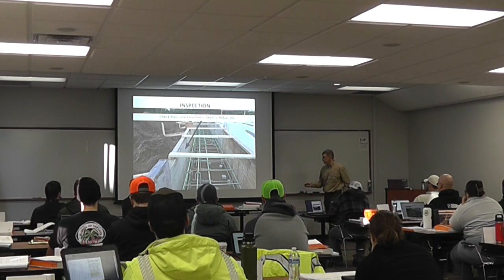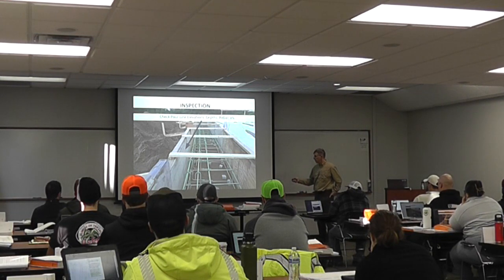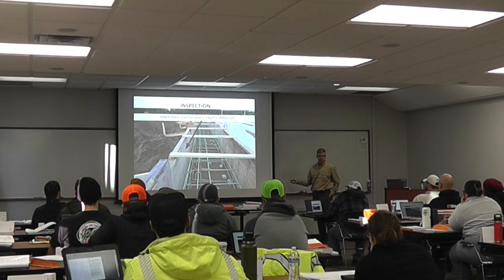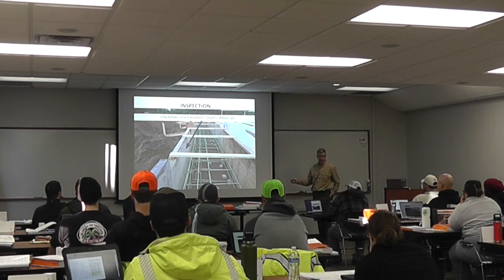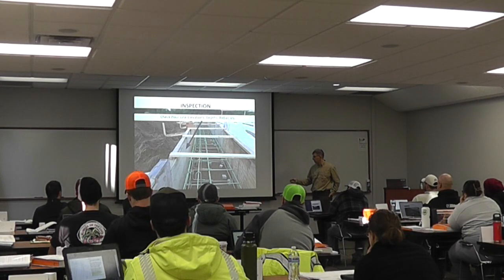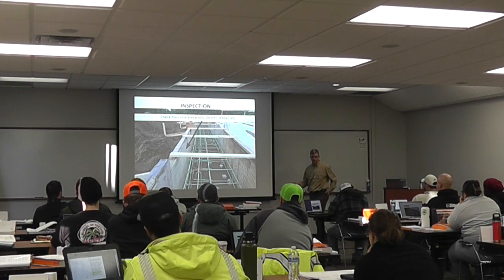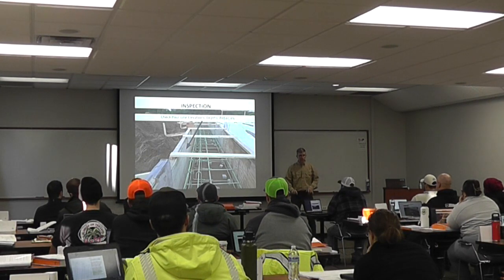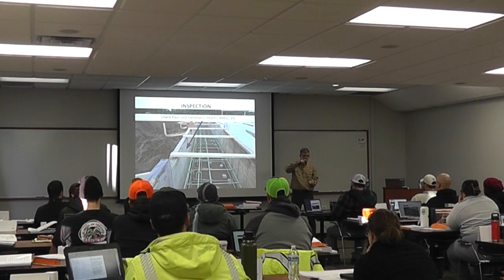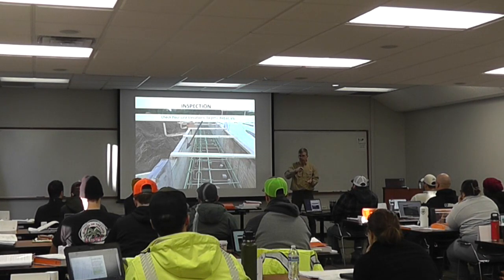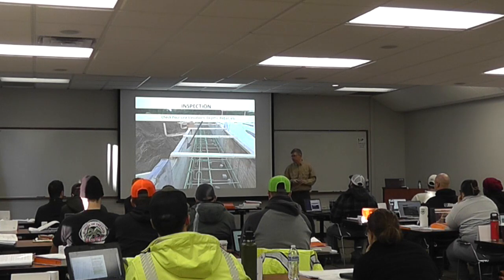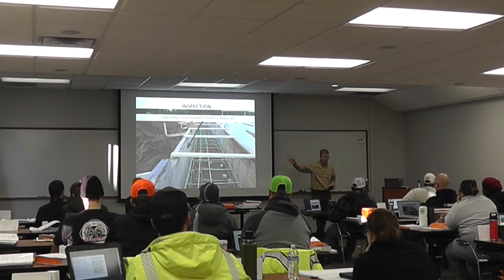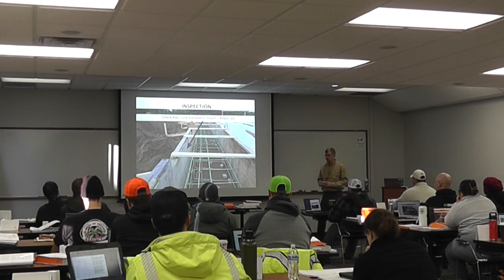Yep, good point. I was just going to mention that these are called Dobie blocks, is the name that they use. We cannot use those in things like bridge decks, but we can use them in this situation in spread footings. They're little blocks that they literally set the rebar on so the rebar wouldn't sink down. You've got to keep the rebar so that concrete can get all the way around it to make it structural. But yeah, good observation. That is exactly what they're for, is to put the rebar on there. So Dobie blocks are what they're called.